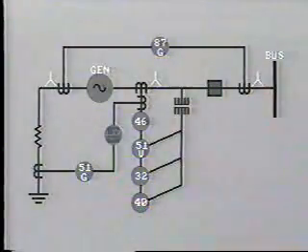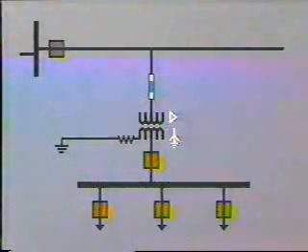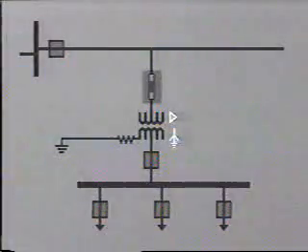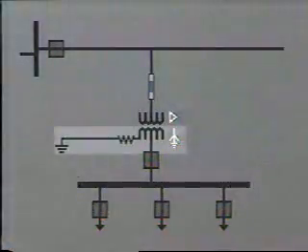In an earlier tape, you will remember we discussed the application of this relay to generator protection. Another typical application is with the distribution substation transformer where the high voltage side is connected in delta, protected by fuses, and there are no CTs available. The secondary side of the transformer feeds through a breaker into the substation bus, from which various feeders are tapped off. The secondary side of the transformer is Y-connected and grounded through a resistor.